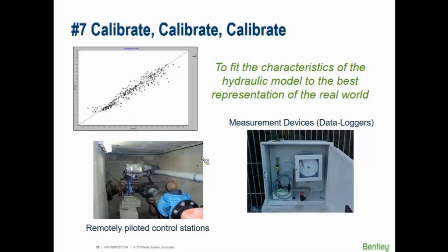Then once you've got the model skeletonized, if you needed to, maybe it's just laterals. Maybe I'll take a step back. Maybe you just want to take off the laterals in the system or remove pipes in series and simplify the network. That's an example of skeletonizing. That's not bad. It's okay. It just helps you move faster as a modeler.